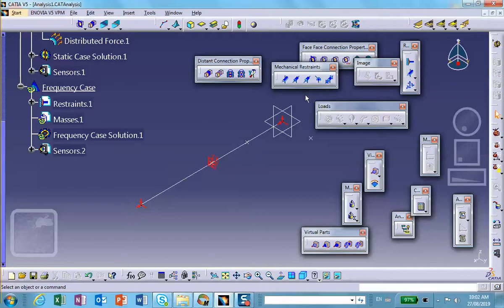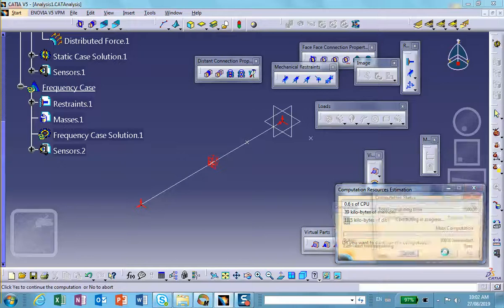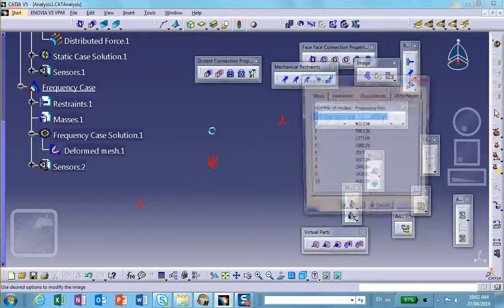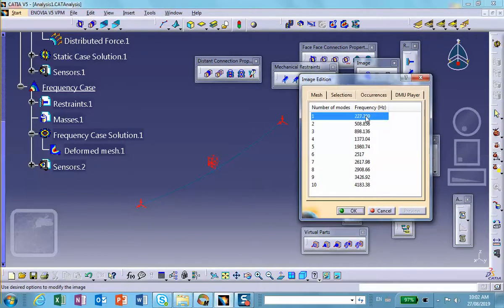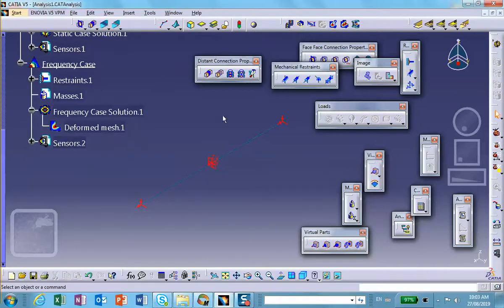Run it. And let's look at the frequencies. Now notice that some of these are bending, some are axial. So this one is bending, this one is bending, this one is axial for sure, okay? And this one was axial. So keep in mind that these 10 frequencies, not all of them are appropriate for the kind of thing that we want to do for bending mode. But anyway, let's leave it the way it is. We're not going to worry about it right now. Now, once this is done, we save. Save. Where's the save? Right there.